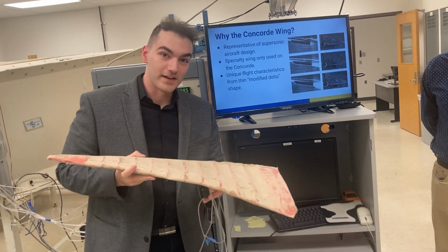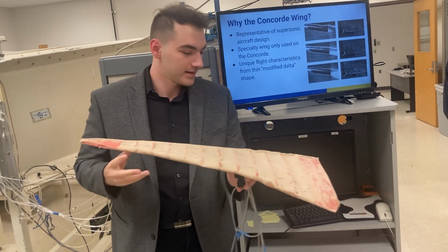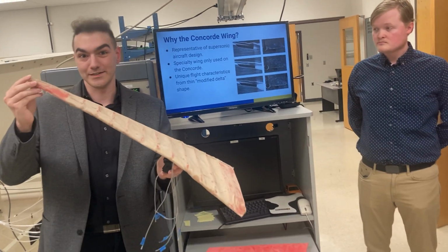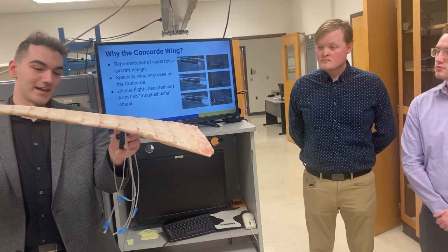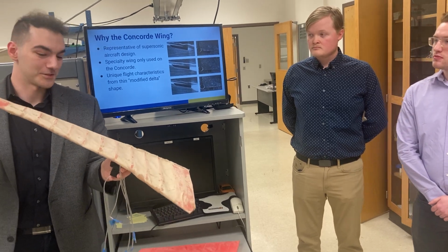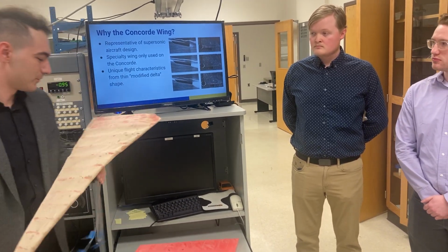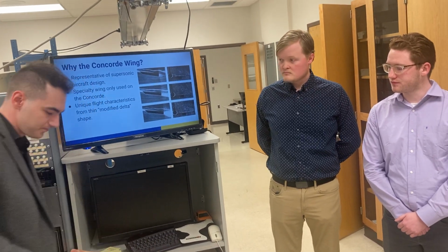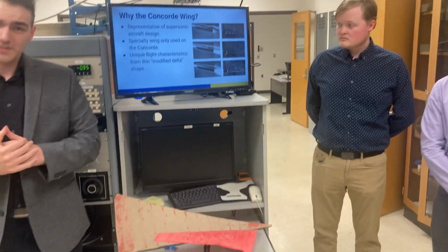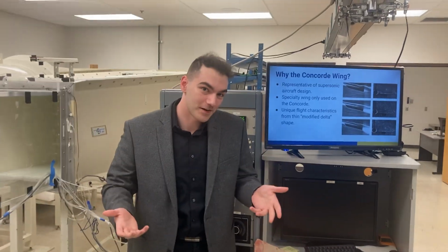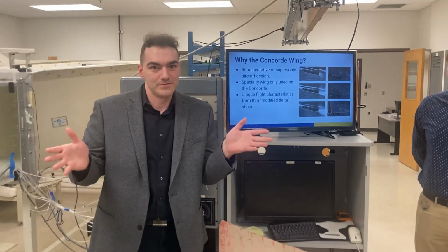The takeoff angle, which is pretty much the most extreme angle you can expect on a 707, is 11 degrees. A takeoff angle on a Concorde is over 18, which, if you factor in the actual angle that's mounted on the aircraft, is over 20 degrees from the horizontal, which is very impressive. Which is part of how it actually generates lift, by using these specialty lift characteristics. Certain other supersonic aircraft do this, but none to this scale of applied speeds. There are obviously certain fighter aircraft and things that do this, but they aren't to this weight.